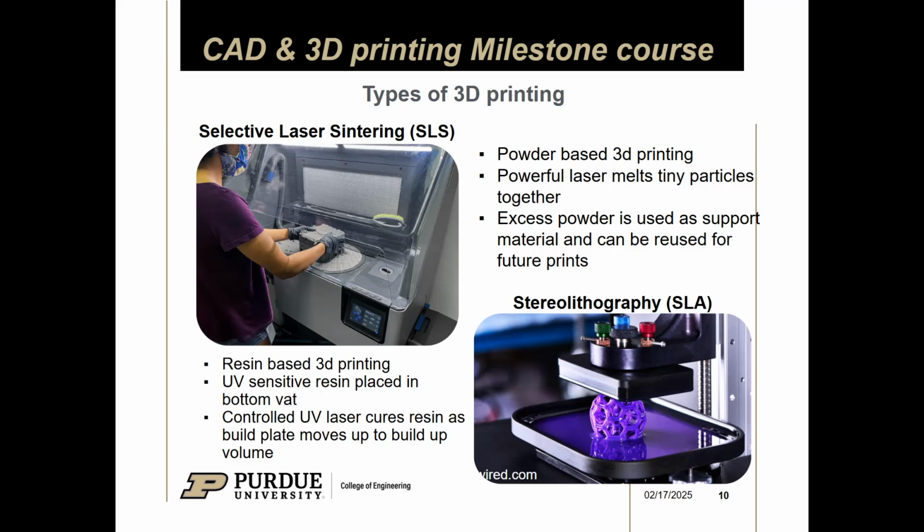Obviously, there's a bunch of different types of 3D printing. On the more industrial side, you'll see SLS or SLM 3D printing, and that's basically when you take a powder and use a laser, that's where the L is, to melt the part, and then you add more powder on top and you melt it again, right? So SLS is selective laser sintering. It's pretty cool. It can get pretty expensive, but it is a great process. You can get a lot of strong materials, including metals.